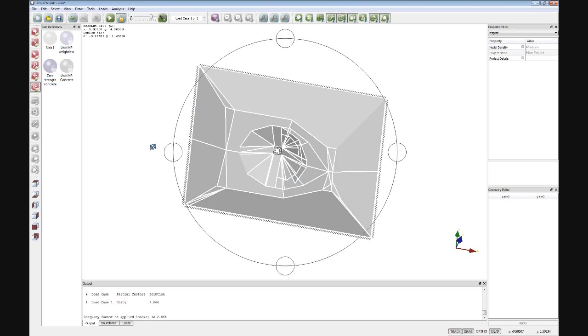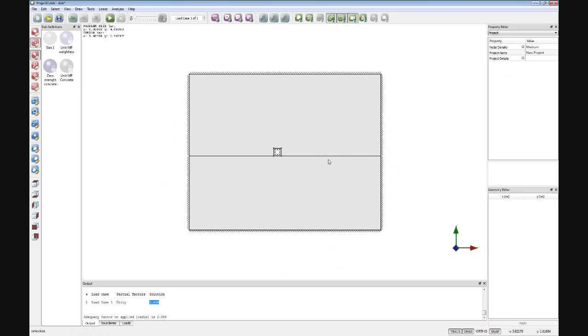So we've done that, we've added a column to it. We've seen here that the adequacy factor is just over double what we had originally, so it's gone from 1.22 to about 2.86. Another thing we might want to do in this case, if I unlock it, is change the boundary conditions around the edges of the slab. So what we can do is to select maybe the right hand side, and on the external boundaries, instead of them being simple supported, let's make them free, so that that's an entirely free edge. We've got this column still in the middle.